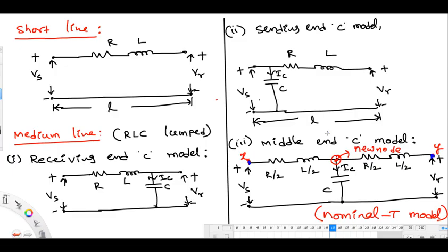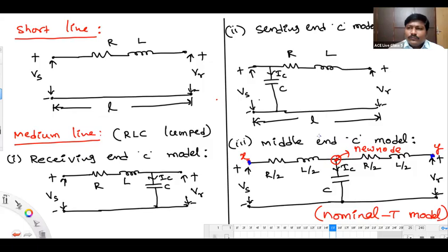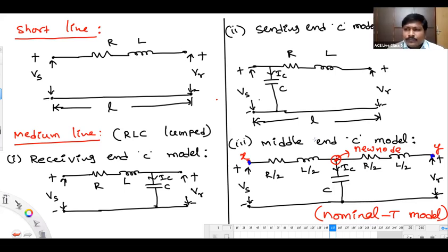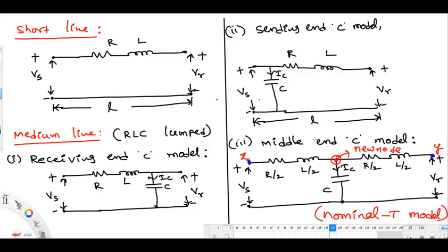Hello. Tell me, Vishwanath. Sir, I have a doubt in calculating the GMD of the system. Okay. Suppose we take three conductors which are at distances D and 2D, how will we calculate the GMD, sir? I take the cube root of GMD of A into GMD of B into GMD of C. Okay, that's also correct. But the answer will be wrong, sir. I get a different answer.